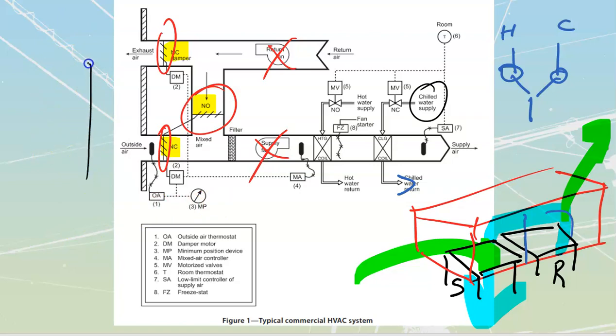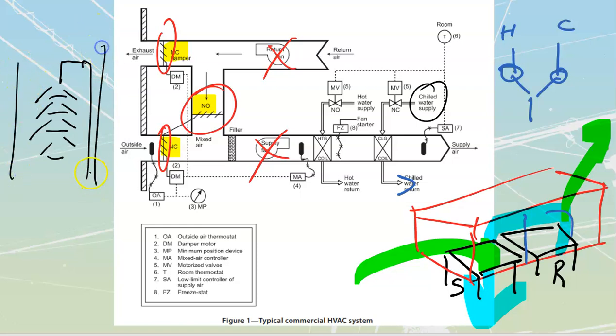So what we'll do is we will actually pump it, and then it's going to cascade over a series of baffles that are going to be inside of there. What those baffles are going to do is break up what we refer to as the laminar flow, the way that the water would otherwise be flowing through there. And this is all happening inside of that tower. It's not splashing out or anything, but it's going to break it up and expose the surface of the water to the air so that it is going to be able to lose its heat.